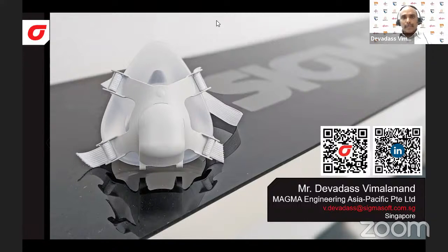But wherever you want to put the thermocouple, it should be repeatable in the actual mold. If you want to put it in some place that is not possible in the actual mold, then it does not make sense. But in SigmaSoft, virtually, you have no limitation. You can place the thermocouple wherever you want, either in the mold or in the part or in the insert. There is no issue. You can put it anywhere.